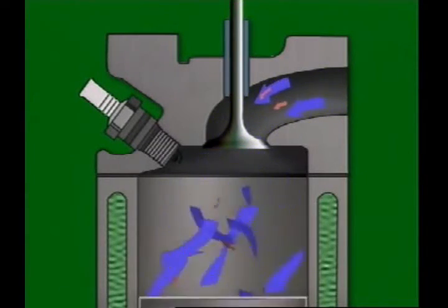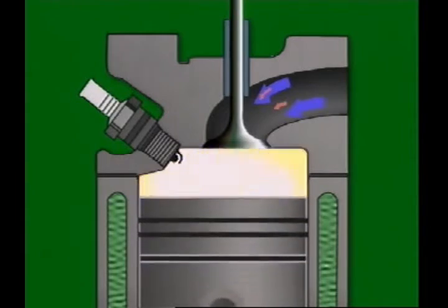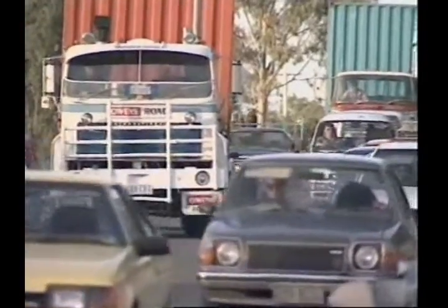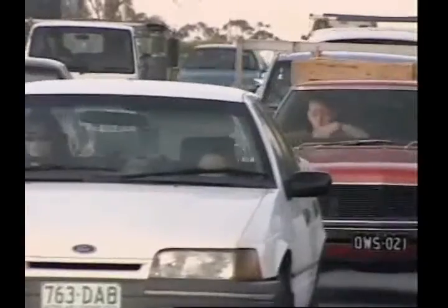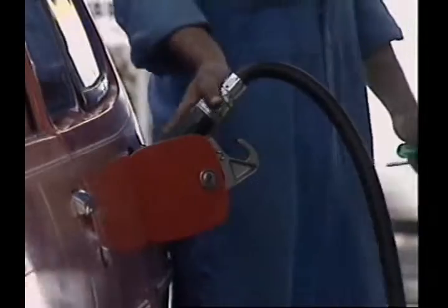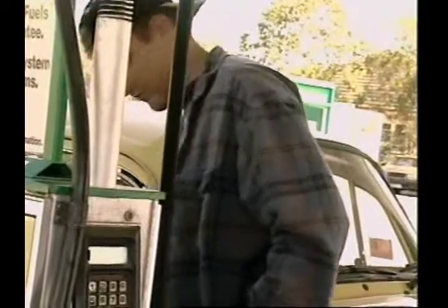Higher operating pressures in the combustion chamber can also cause abnormal combustion. A lead-based anti-knock additive used in leaded petrol can allow these higher pressures without loss of performance. Lead additives are also lubricants. In high compression engines, lead compounds coat valve faces and seats and help prevent wear. Leaded petrol is used in older cars that have few or no emission controls. It should never be used in engines designed for unleaded fuel.